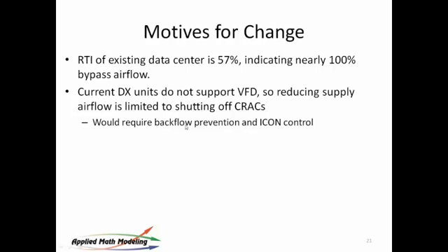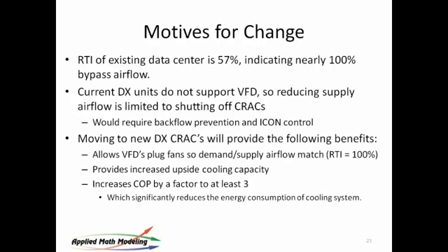There's also this issue of backflow. Once you shut one down, you should have flapper valves underneath it or on top of it, depending on how you've configured it, that shut. Just gravity, passive one-way valves, backflow prevention louvers that allow the system to fully shut. So in this case, VFDs was something the customer wanted to do. They were trying to make an argument for getting those DX units out of there and adding VFD-based systems in.